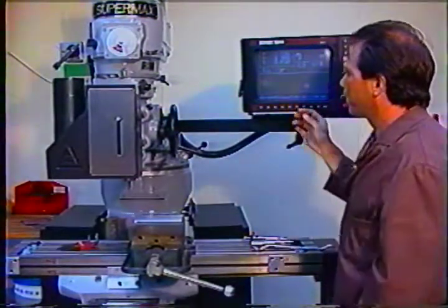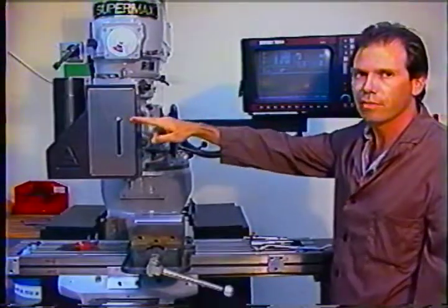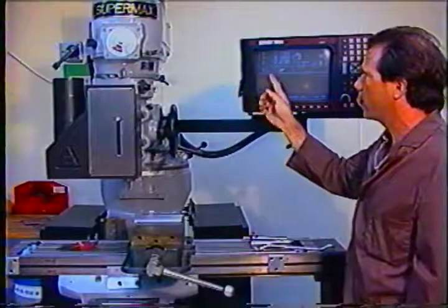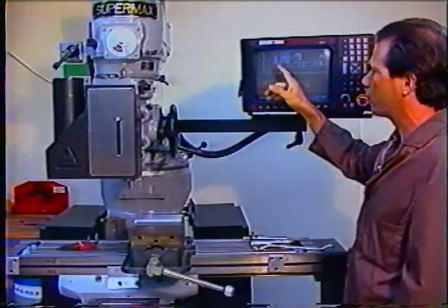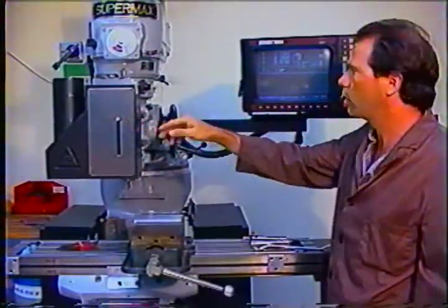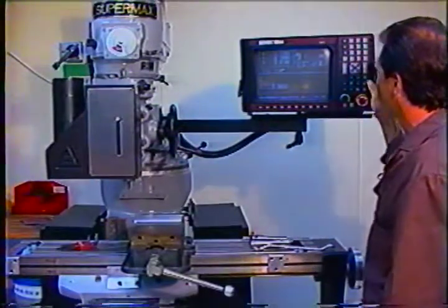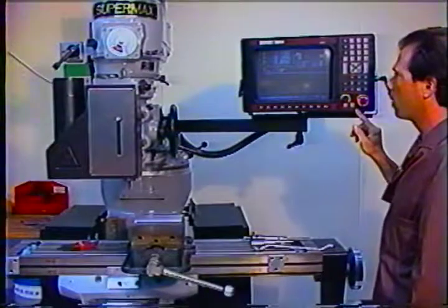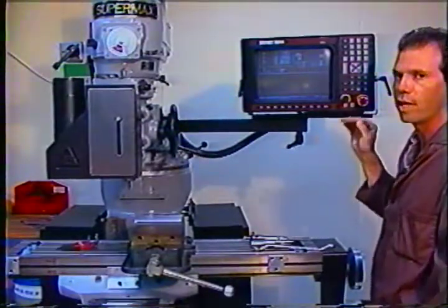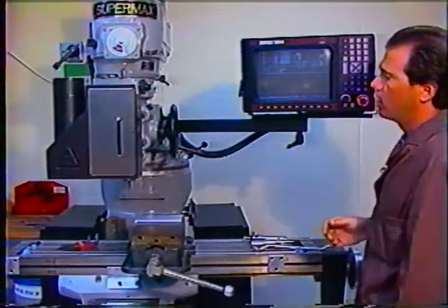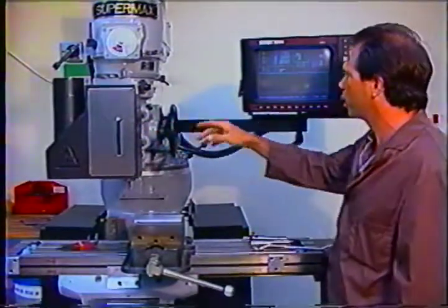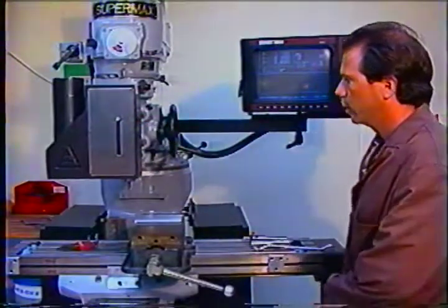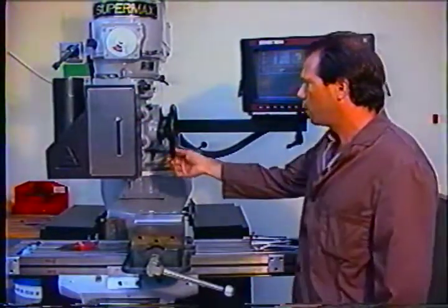Okay, now we need to set this position to Z home position, or tool 0, Z0. Tool 0 is active. We're not at Z0. I want to make this position Z0, so I simply press Z0, enter, enter. It's very important, not start. Start would have driven it to Z0. Enter sets a new Z0. So now our Z home position is set, and we double check tool 0, Z0, we're near the top of our travel. So now we're ready to do tool offset number 1.